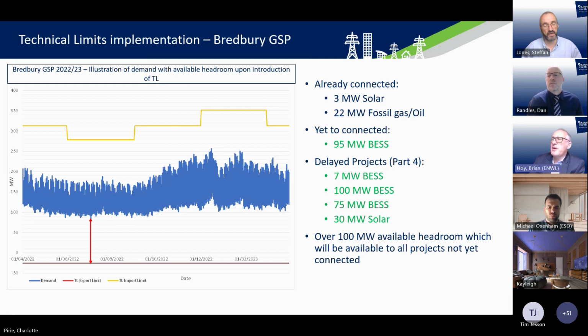Yeah, I was just flipping back to this example, which shows the real capacities. There you've got just over 210 megawatts of extra generation to connect, but it all depends when they are trying to export. If they're not coincident, actually all of them would sit under that, at the very worst you've got 100 megawatt threshold, so any one of them can operate, possibly in combination 2 or 3. As long as they're not coincident, they all could be connected and happily exporting, not quite to their heart's content,